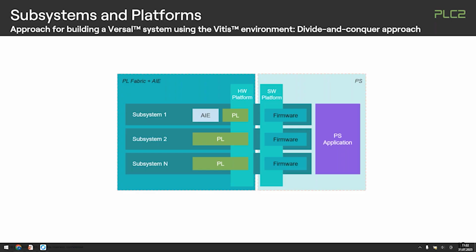So this firmware layer actually can access a representation of the hardware through software means, and that's what's called a software platform. It's something that you create from the hardware side, where you pick up your address map and you add the drivers to the particular items, and that's the actual thing that you have to look at.